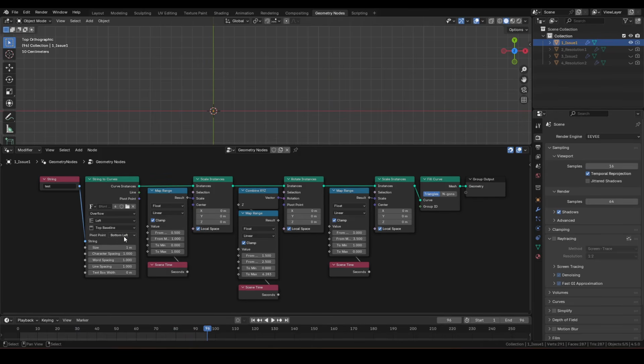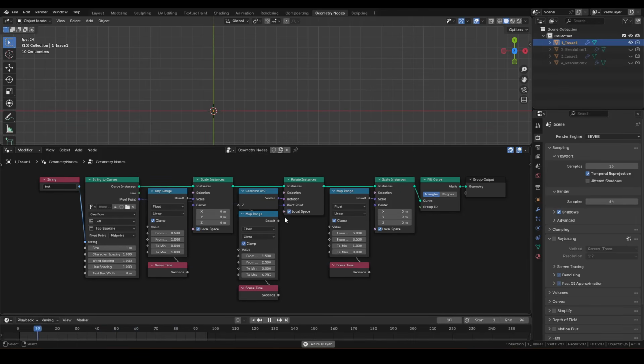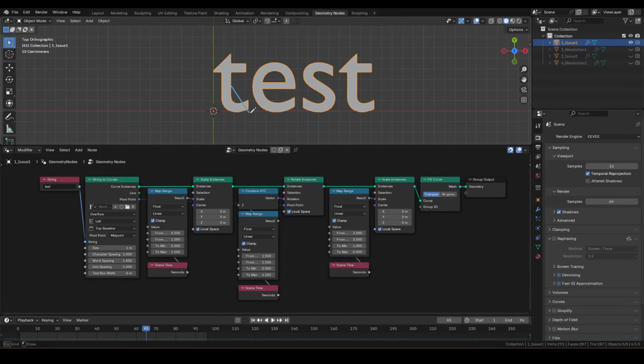So if we set this rotation pivot point to midpoint by connecting these sockets, we end up with a more compact rotation with a completely different motion. The issue arises if we want to set the pivot point to bottom right for the second scale. We cannot use the provided pivot point because it is already used up. If I change the pivot point to bottom right, it will affect the rotation animation. So this is inconvenient.